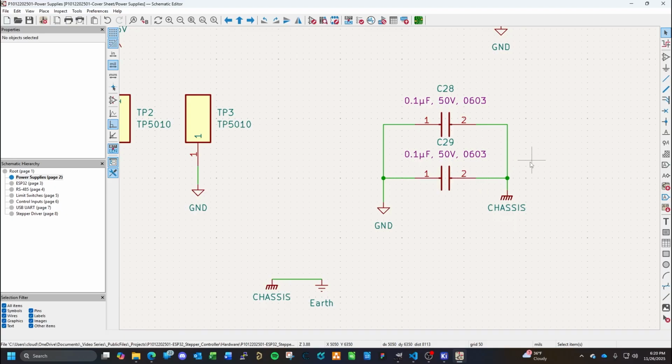So there'd be a bunch of math and investigation to do to figure out all the right values for your stitching capacitors, your capacitance values, and the voltage rating that they have. Mainly, that's what that is. They're isolated, but yet they're stitched together in a way that the capacitors would allow that real fast voltage differential to jump over.